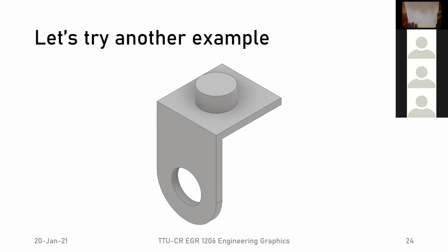Yes, the only problem with the compass is that getting the right line thickness is sometimes difficult with a compass. And also for the next step that we'll do, this one is now going from the 3D drawing to a 2D drawing, but next week when we do the opposite, you can't use a compass for the circles anymore because the circles then become ellipses. So at some point you'll have to practice drawing some kind of an arced line by hand. But if you want to, for these where they are circles, you're welcome to use a compass, of course.